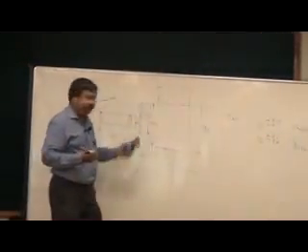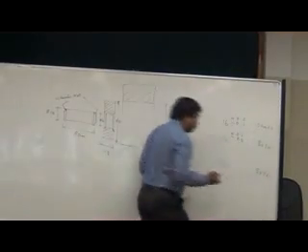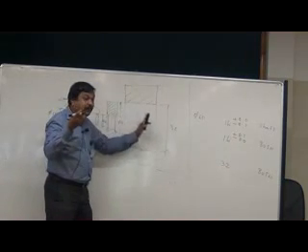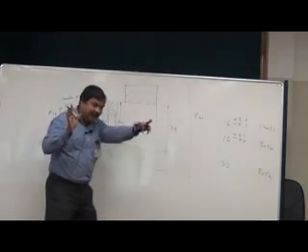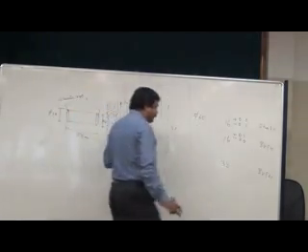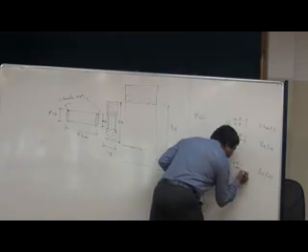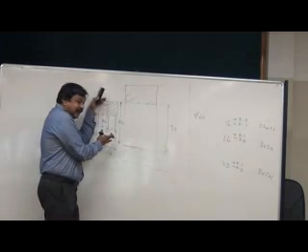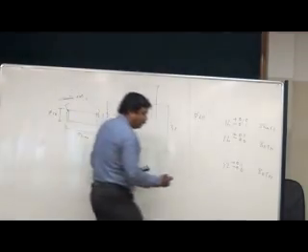Now, coming to this 32 mm diameter of the bush, what I am going to do is make what sort of relation between these two? No relative motion. As he said, no gap. So this 32 mm, I am going to make it plus 0.1 minus 0. So here, the outside diameter of the bush is going to be larger. And what happens to the hole?